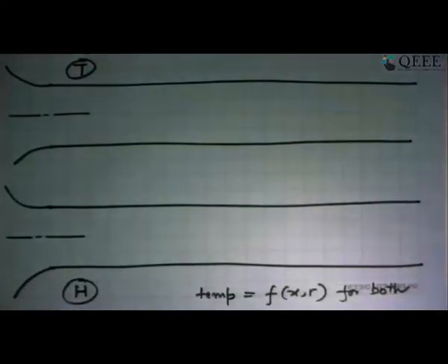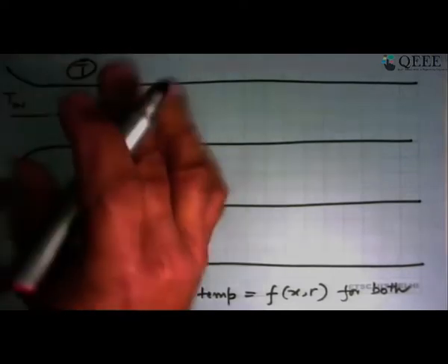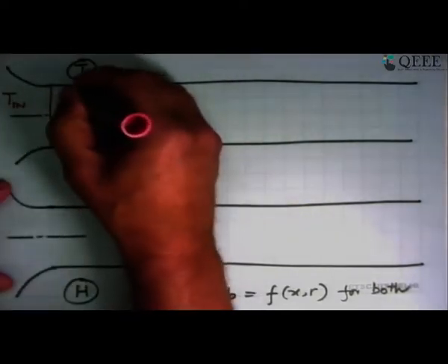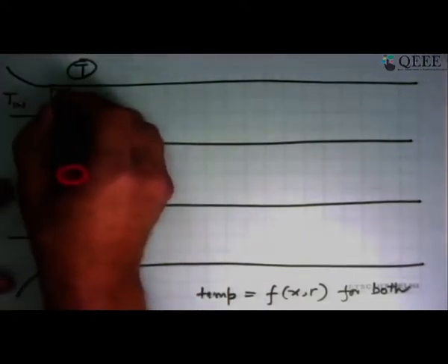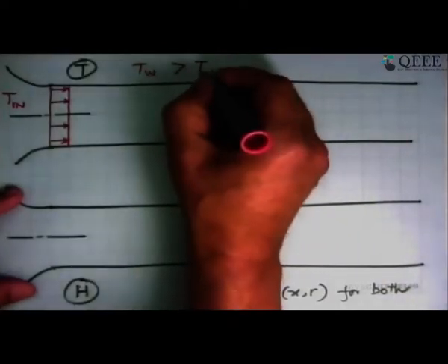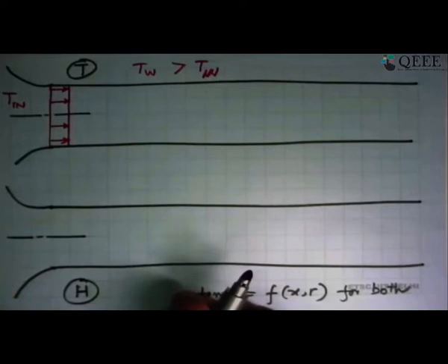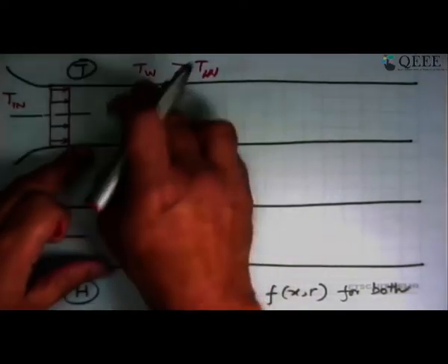We'll develop one important thing, and then that's where I think we'll run out of time, which is that in the isothermal case, let's see what happens to the temperature profile. We assume that the temperature at the inlet was T_in and it was uniform. So temperature here everywhere was this much. And I'm saying again that temperature is being shown by an arrow only to show the magnitude, not the direction. It's a scalar. And T_W, let's say, is greater than T_in. Thermodynamics tells us that if the tube is very, very long, infinitely long, and you keep blowing, this fluid will finally everywhere come to the T wall temperature, and that's the maximum you can get.